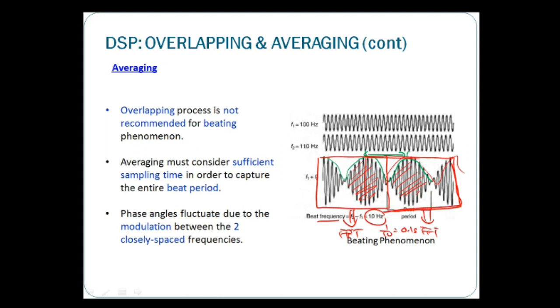So maybe it's 49, another one is 48. Different slip frequencies coming in, then it becomes two close frequencies. If it's exactly the same frequency, then no issue. But because you have some difference, that will cause fluctuation of your vibration amplitudes over time.